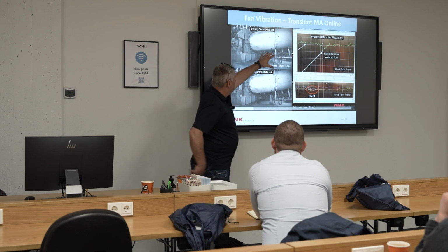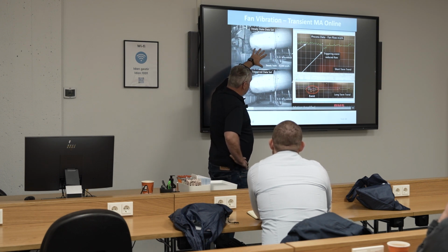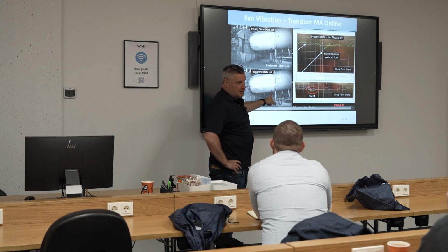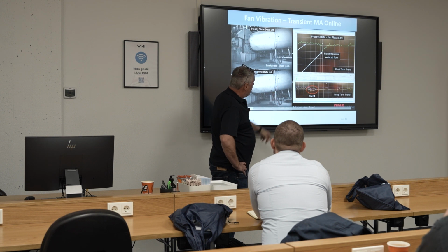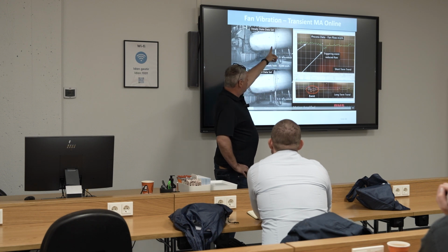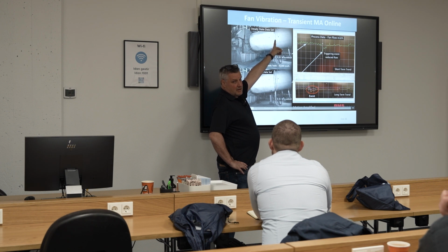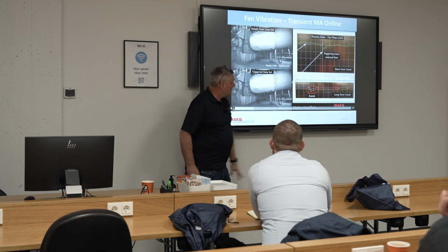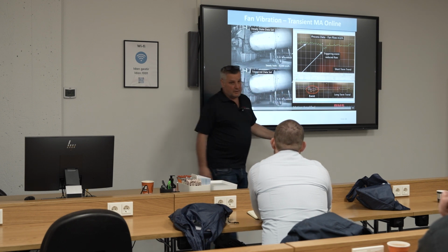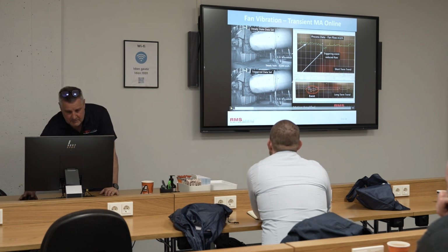So basically this inlet to this fan has different flow states, but only at certain times was somebody noticing this vibration in the bottom support. Because it wasn't happening all the time, we had to set up a camera over a CM server to look at all this data and use it as a trigger. We set it up so that only above a certain trigger did the camera start recording, because normally it was okay. Over the long-term trend, it proved that when the flow rate became lower, it caused this brace to move about.